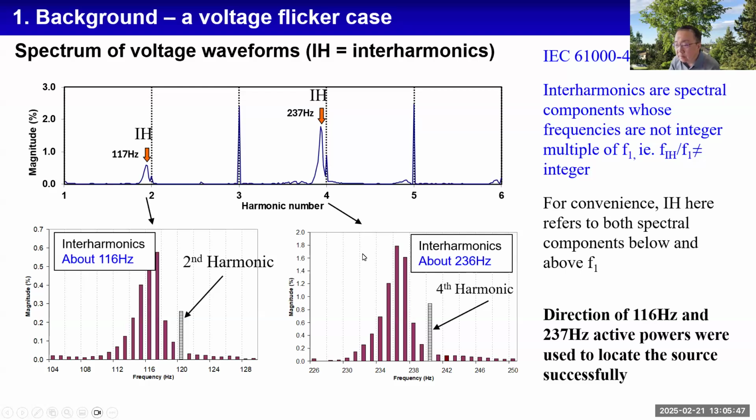In this presentation, and in all my work, I don't differentiate spectrum components that are below or above F1. I call everything interharmonic components, just for the sake of convenience. Some people call spectrum components below the fundamental frequency subharmonics. Here, subharmonics are also called interharmonics.